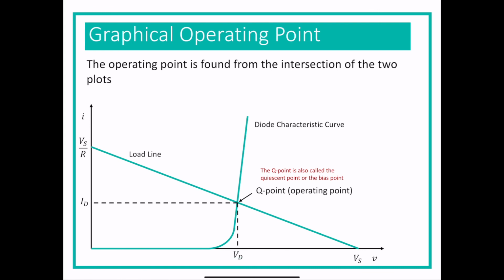The problem is that frequently the diode curve has a very, very low resolution because the voltage only goes up to 0.7. And usually your source voltage in the circuit is like 5 or 10 volts. So often resolution is lost because the diode curve gets crammed into the far right of the graph, and then the current ends up being way up close to the maximum current.